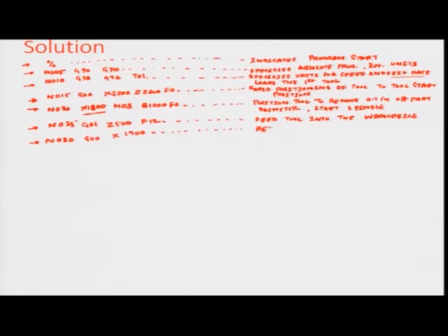Remember, we had gone up to 1.8 diameter and we are now going to 1.9, which is actually towards the right of 1.8, and so it is still clearing off. So, we will say this is a retract tool option and overlap previous cut.